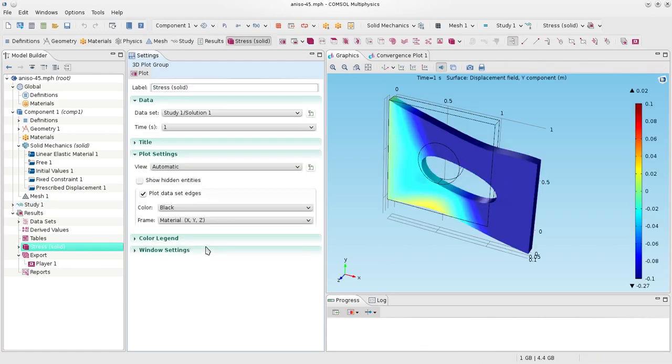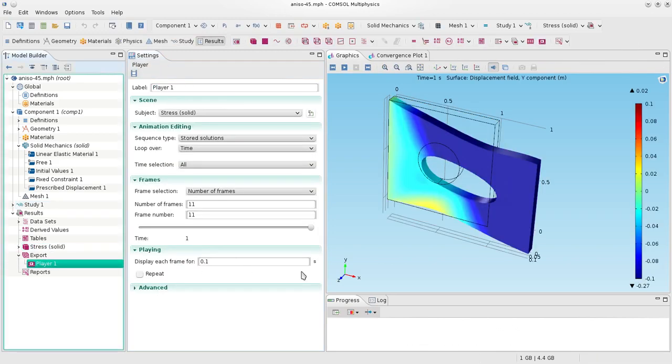And that's the solution. Okay, so we're going to go ahead and plot it, but before we visualize or animate it, we see already that all the colors are almost blue except for this portion, which means that everything is moving down, and I see that visually, of course, but the colors just highlight it even further. So remember, I only applied a displacement along the x direction, and the plate is free to move along the y and z directions.